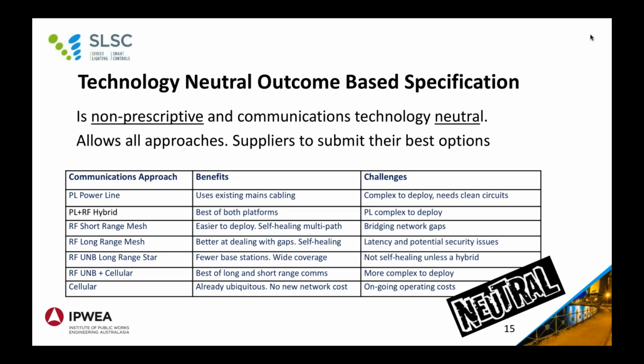Yes, that's a very important issue. In terms of the internal communication device protocol within the luminaire, there are two options, DALI and 0 to 10 volt DC. There is a strong groundswell internationally towards DALI as a digital addressable lighting interface, and that has a broad number of asset management attributes that many large procurers such as councils and in particular DNSPs are taking up, as the ability to actually inventory and identify a broad range of complex issues regarding the luminaire and the control system can be stored and accessed. So it's an important issue.